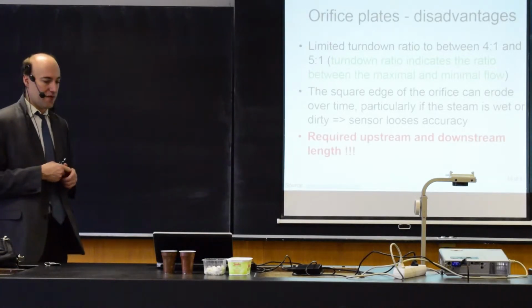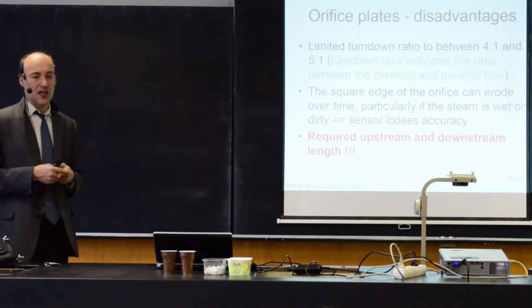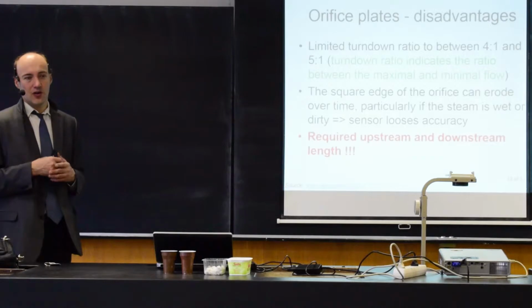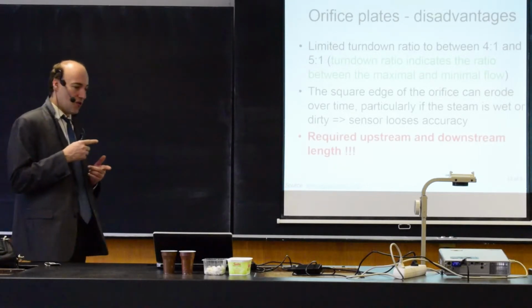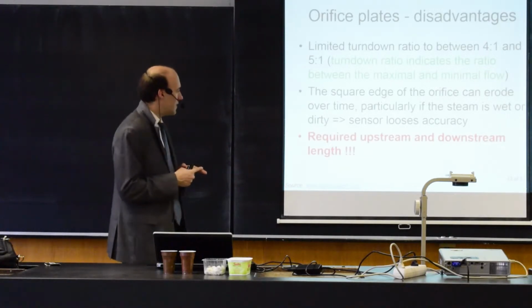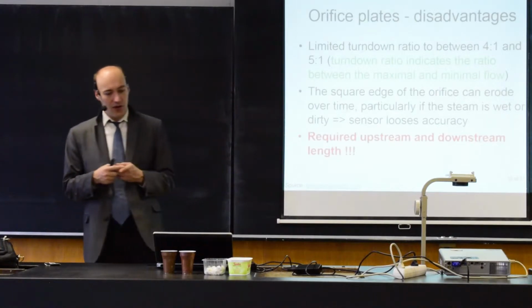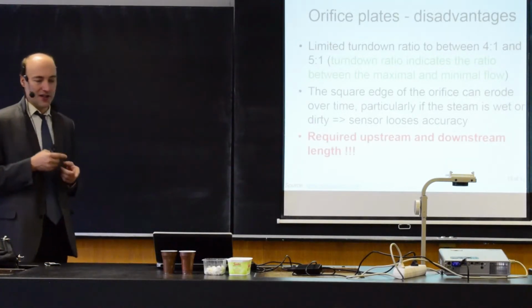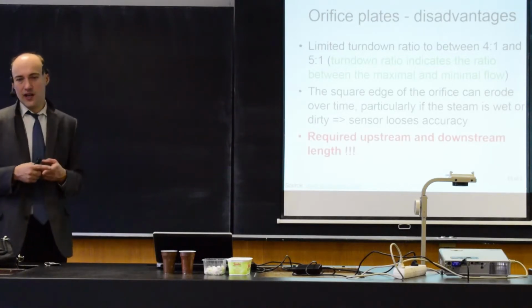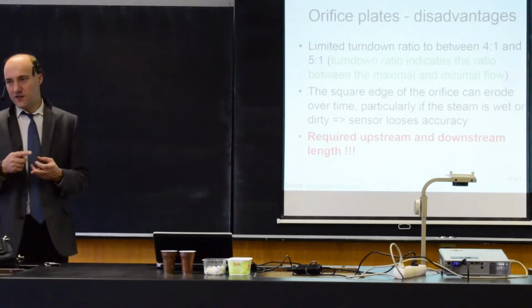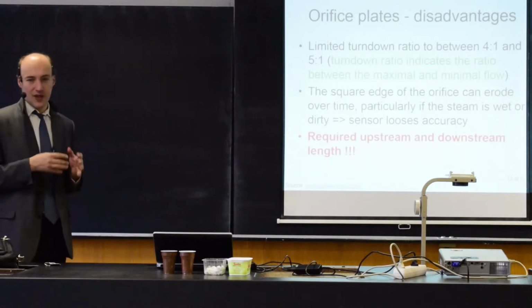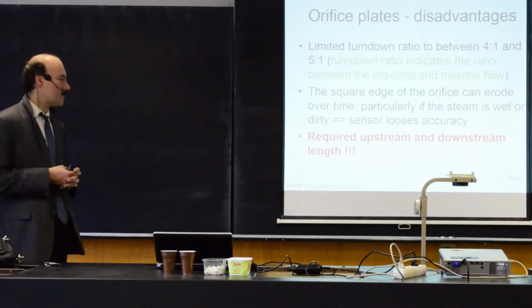So it means if there are particles or impurities in the fluid, you cannot use an orifice plate. An orifice plate can be eroded over time by the particles in the fluid, and therefore you can use it only for clean liquids, vapors, and fluids. So it's only for clean mediums.